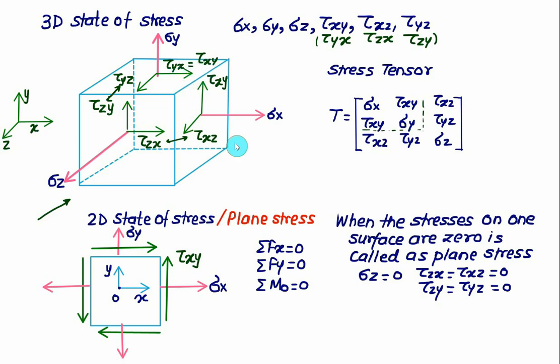The major purpose in looking at the stresses on different planes is to determine when a stress state produces failure. Failure of a material is complex, and a solid understanding involves knowledge of both material science and mechanics. Mechanics of materials, and stress transformation in particular, are needed to determine the combination of normal and shear stresses at which failure in the material would occur.